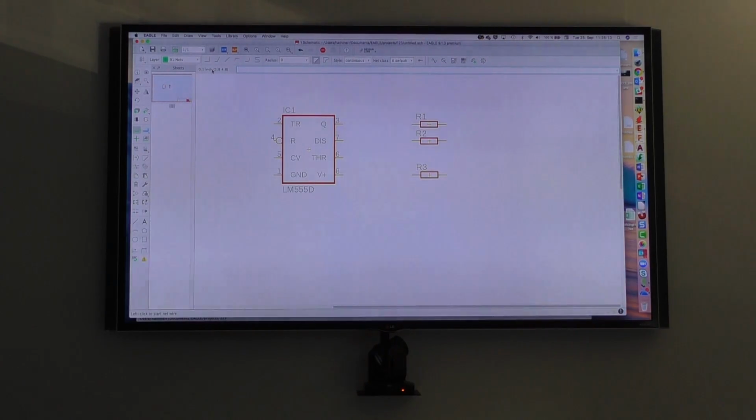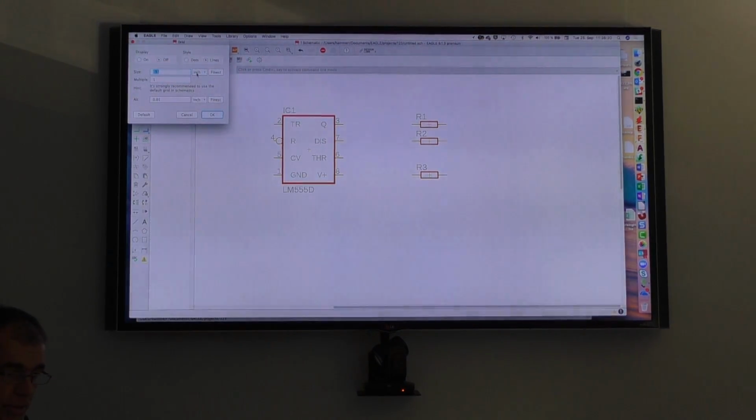If you prefer to see millimeters here, there is a grid icon, this one. And then I can switch to millimeters if I want to. It's 2.54. If we had met a year before, I would have said never change this grid, because if you change it, for example, to 2.5, you would never get a connection from net and pin. Meanwhile, that's not a problem, because even if I change the grid, the net jumps onto this connection point of the pin. No problem at all.